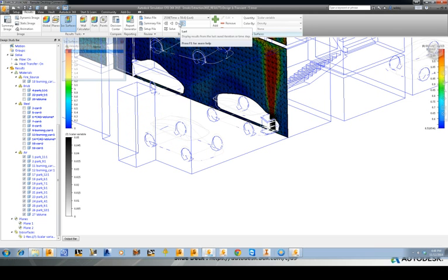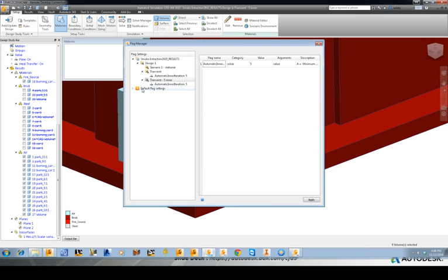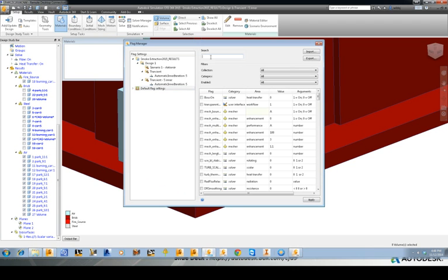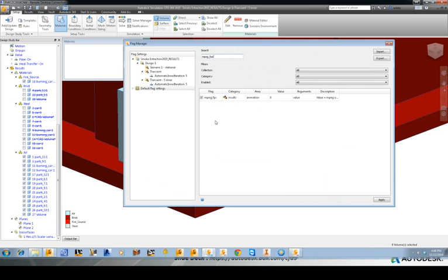What I will just share actually, while we're waiting for any more questions before we bring the call to a close, is that when we're saving out MPEGs, I find that generally the frame rate is terrible, and they either occur really quickly or really slowly. You could see the animation that I had in my PowerPoint was really, really fast. We can use a flag to control the frames per second in the MPEG. So I've used a value of 8, although when I click on it, it changed to 1. If we reduce that value, we should be able to slow the MPEG down a little bit.